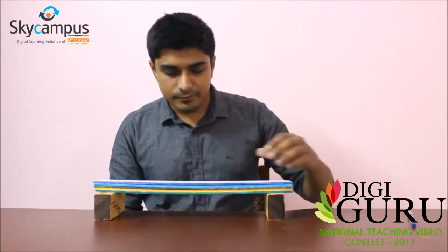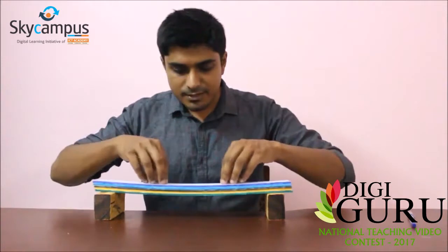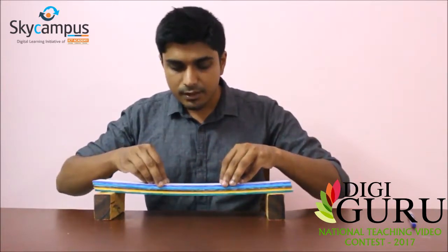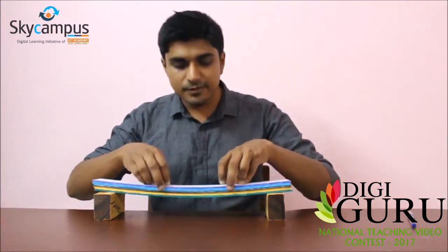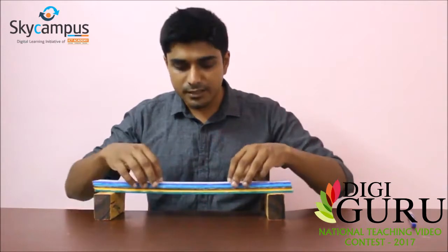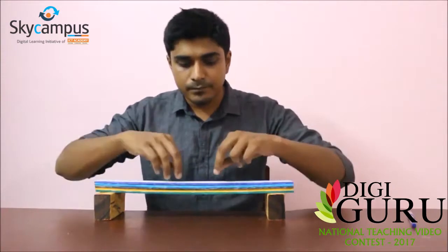Now let's take a look at how shear stress is developed in a beam. We have seen before that the amount of strain or the amount of elongation or compression on a layer depends on the distance of the layer from the neutral axis. Let's take a look at the first two layers of the beam. Now the first layer, the topmost layer, undergoes a little more compression than the second layer, and this difference in compression causes a shear in between these two layers. There is a shear happening in between these two layers when the beam bends,